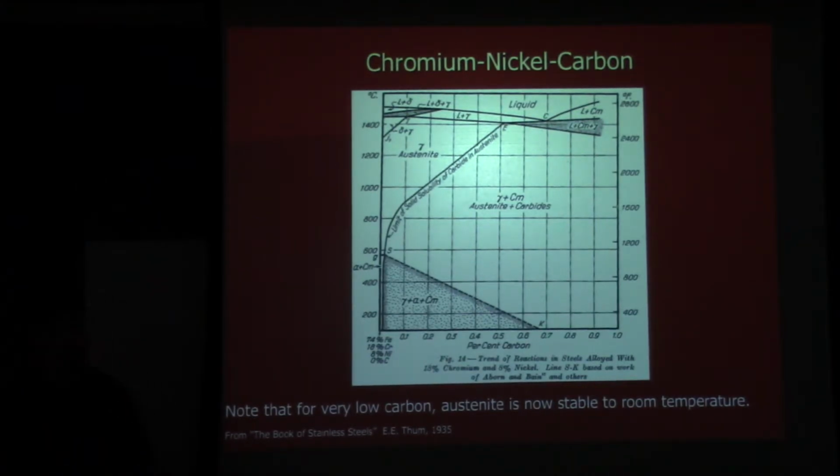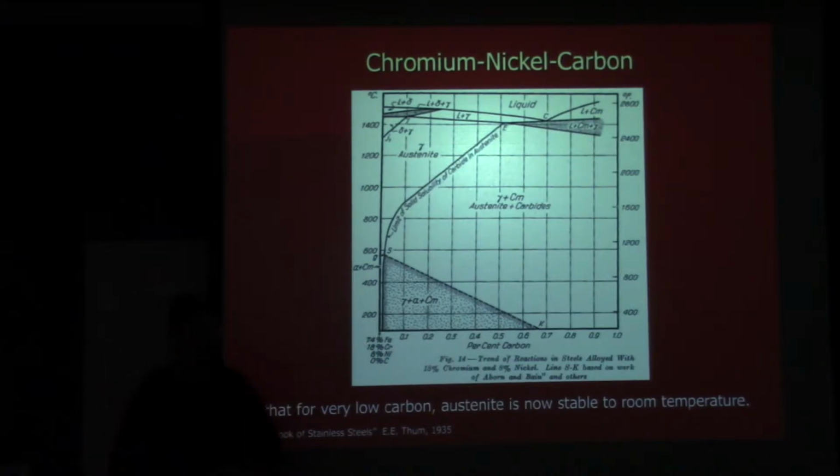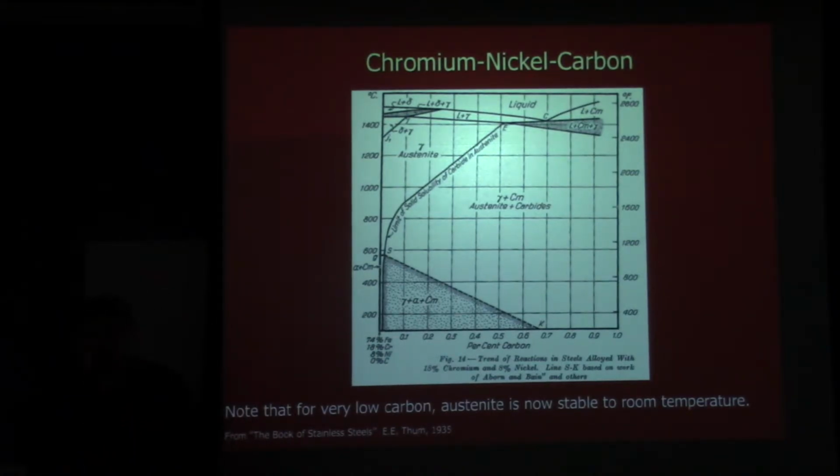So you typically see in grades like that where carbon is capped at, say, 0.03%. So orders of magnitude smaller than what we've talked about so far. When you do that, you can get austenite stable all the way down to even the temperatures of, say, liquid nitrogen. And so when you want to move liquid nitrogen from one place to another, you put it in a container that's made out of an austenitic stainless steel, because it stays austenitic, which is nice in that it stays tough. So if you drop the container, it's not going to shatter.